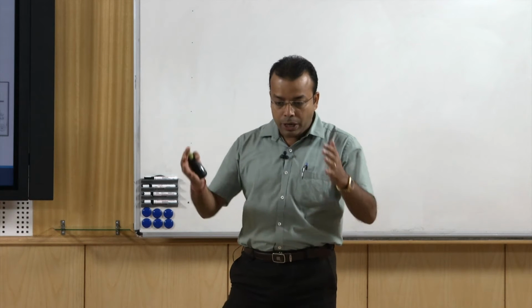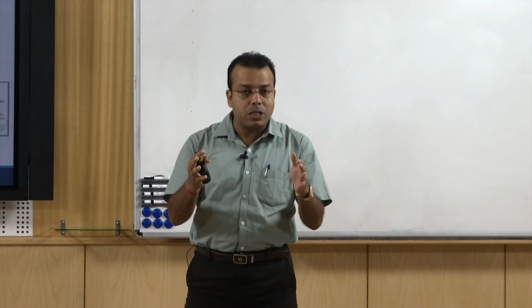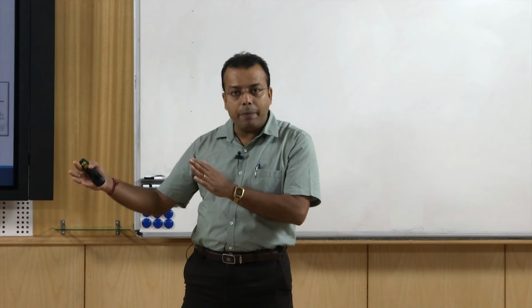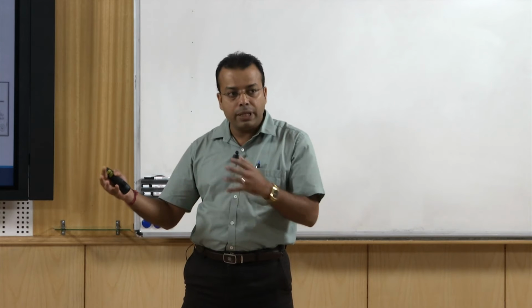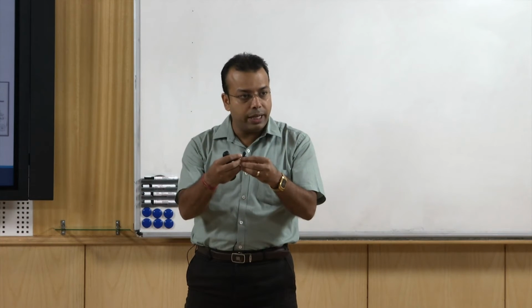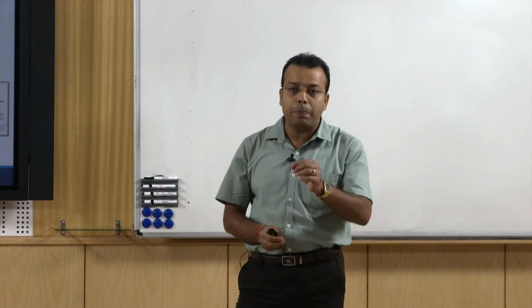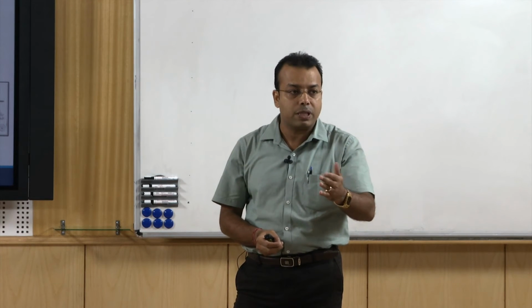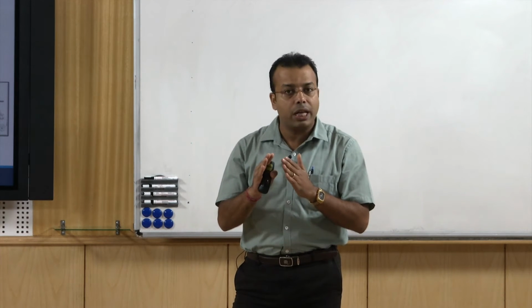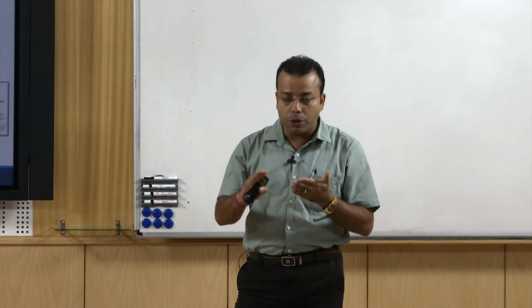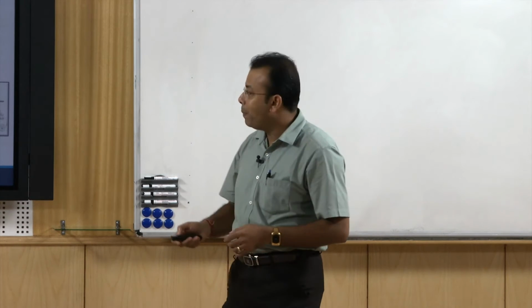What you have to do? You have a container in which you put your abrasive particles, and on one side you have a compressor which generates compressed air. Then your abrasive particles mix with the air, and with a high velocity you throw those particles onto your material surface, by which rubbing or friction takes place, and your material outer surface gets cleaned. That is known as blasting.